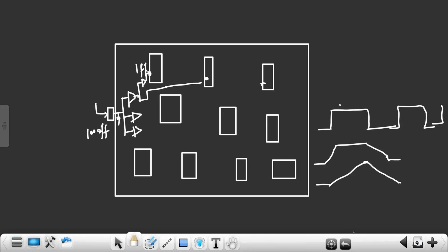To reduce the load, again I will use one more buffer here, means to reduce the net length. More net length, again more capacitance. So on this buffer, again I will be having more load capacitance. To reduce that, I will use one more buffer. So this I can directly connect here. Use one more buffer, connect here. Here use one more buffer, right? Connect here. So this buffer, right? I can connect here. This I can connect here.